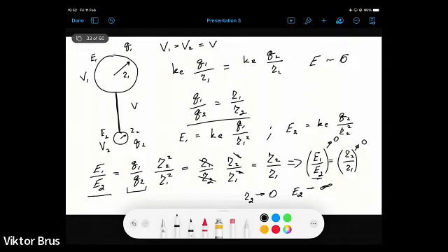Because it could be quite a dangerous situation when we deal with high potential equipment. A very strong electric field can cause ionization of air molecules. They start to emit some light. That already means losses of electric energy, specifically a problematic issue for power lines which transmit electricity at very high potential difference. Also, some electric discharge can happen, which will short different parts of equipment and cause a short circuit, which will switch off the electrical equipment.